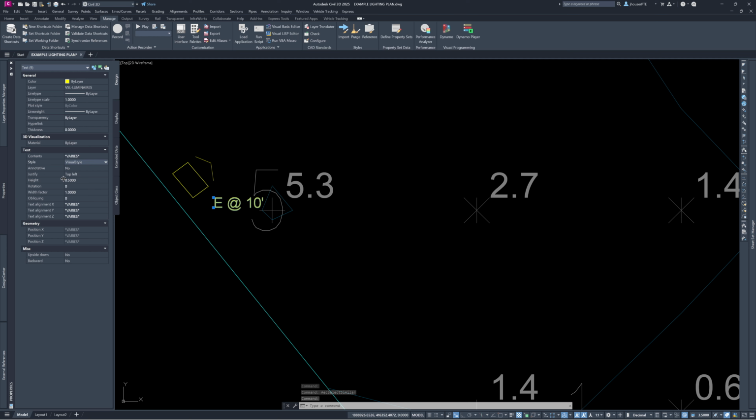Like I said, the CAD line work is not the best. Fixtures get blown up completely. There's probably multiple lines on top of each other. So there's a 3D polyline, and there's three 3D polylines on there. I believe there's also points. Oh, hey, they got rid of the points. Good. But these are also separate out here, so it's still a little messy. It's not a block that you can just scale easily. But you learn little tricks like that to really get things going.